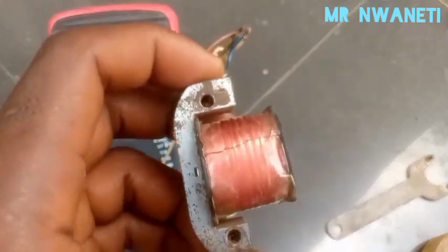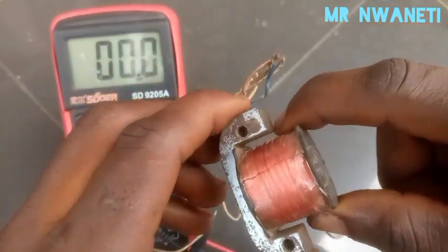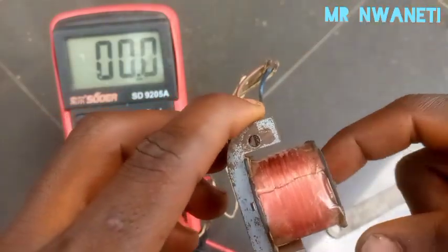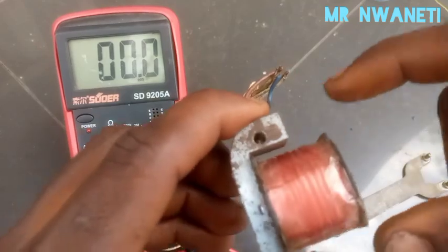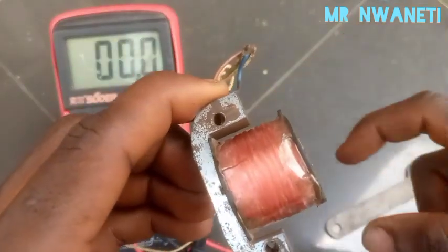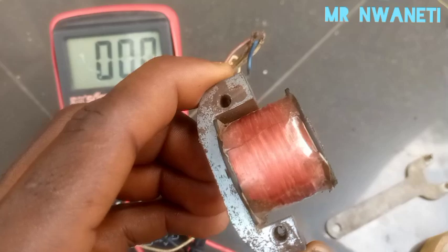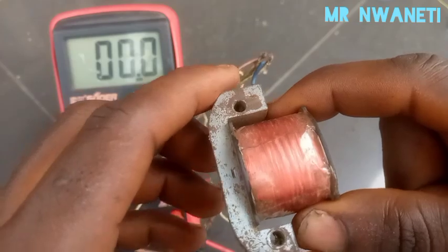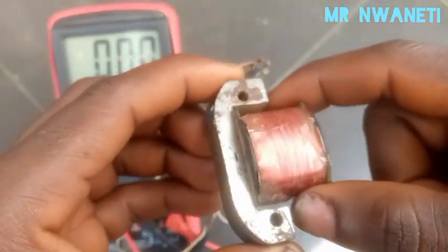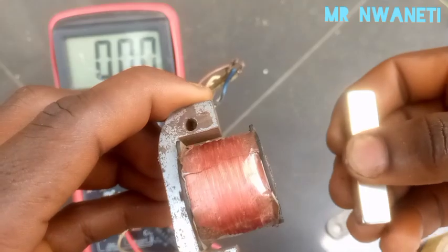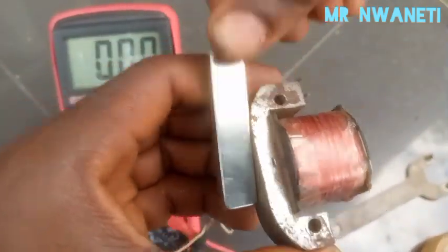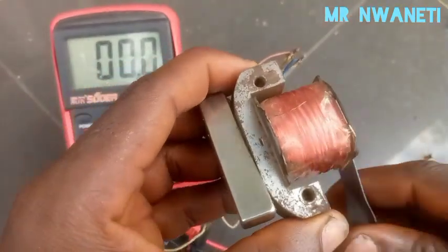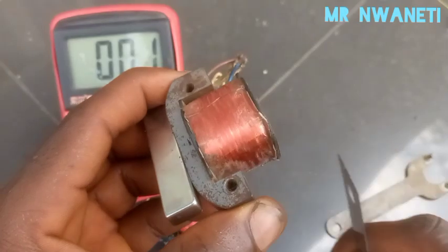But the demonstration is that the main important thing is not the voltage output from the coil, but that when you put a load, you're going to find that the speed of the motor, the driver, will decrease, and when the speed decreases, the current consumption will increase, which is what we're trying to avoid. So how can we avoid this by doing something like this, so that the magnet will be moving. The magnet will be at the back of the coil, held by the iron. Then we'll just be cutting the flux, cutting the flux.